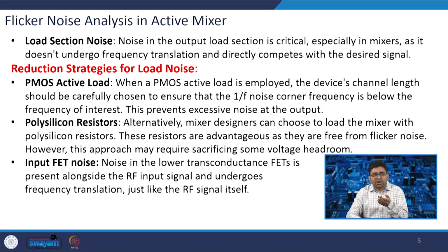Third, we can also consider the input FET noise. Noise in the low transconductance FET is present alongside the RF input signal and undergoes frequency translation. Just like the RF signal, whatever noise is there in the FET will also get frequency translation. So, while considering the design of the load, we should also make sure that whatever active component we are using at the load is carefully chosen.